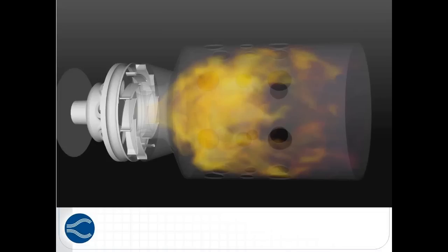But from our experience, certainly the first time somebody reads the geometry into Converge, there can be some issues with the geometry not being watertight or perhaps being dirty. But most often we find that those issues can be resolved relatively quickly.